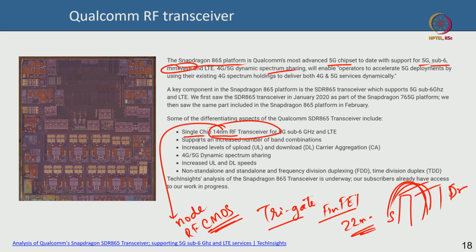platforms that are designed as slightly more expensive, that are designed for RF, such as RF SOI, silicon on insulator. There is a silicon, below that there is an oxide layer, and below that there is a silicon. So, you are basically trying to reduce the crosstalk and the coupling to the substrate, because the silicon substrate is very lossy at RF frequencies. You want to minimize that loss.